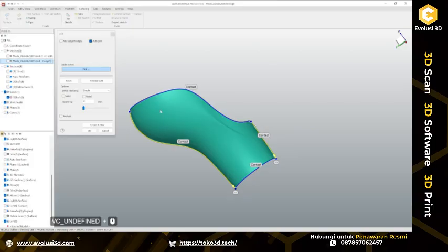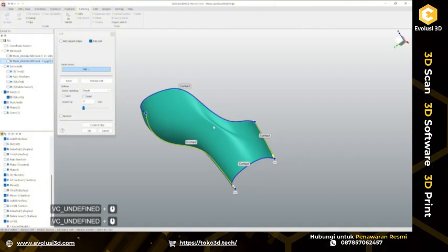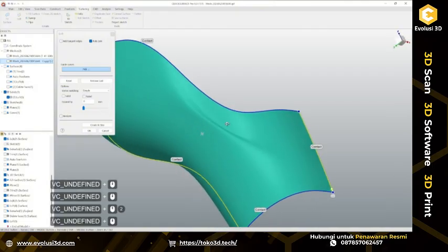And since all of these guide curves start to curl quite a lot, like this, and the same goes for this one, somewhere from here it tends to create the guide curve that we don't see, the middle guide curves inside of the loft tool itself. It starts to create it more or less perpendicularly from this edge here, from this curve, and tries to match it perpendicularly here. And this is the reason why we are getting all of these weird results here.